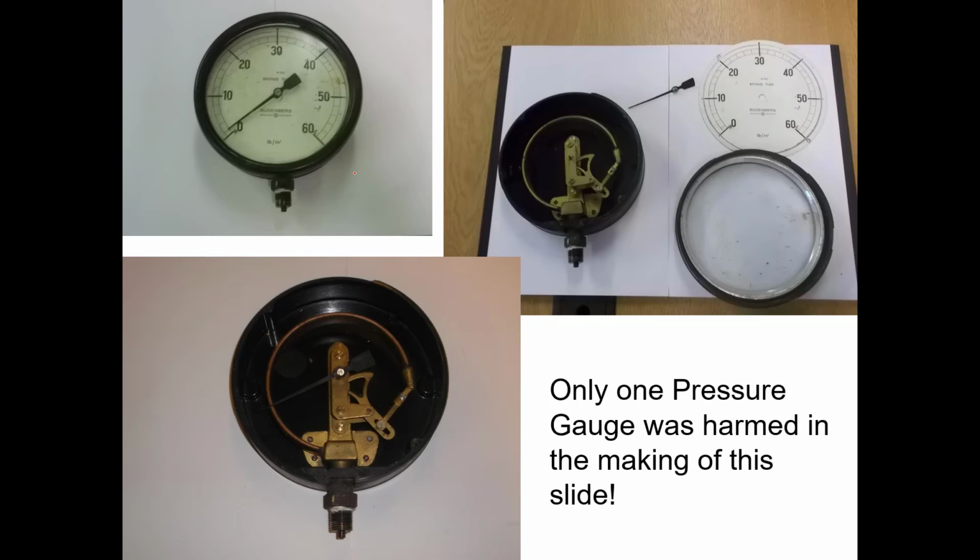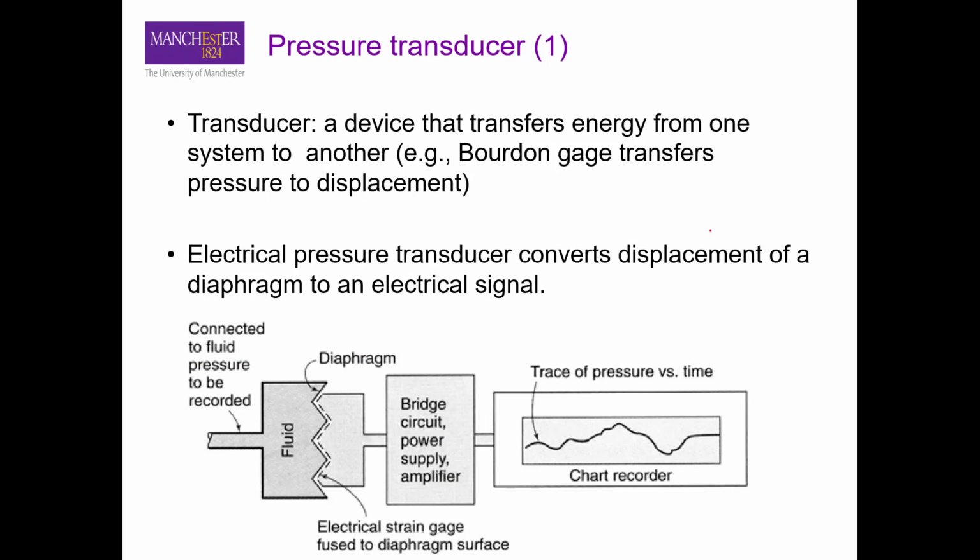So in addition to the pressure gauges we discussed that use the concept of hydrostatics, there are other forms of pressure devices that are also used in industry, and one of the most commonly used is what we call a pressure transducer. A transducer is a device that transfers one form of energy, for example mechanical energy in the form of pressure, to another form of energy, for example electrical energy. So the Bourdon gauge, for example, transfers pressure to displacement of this elliptical tube.